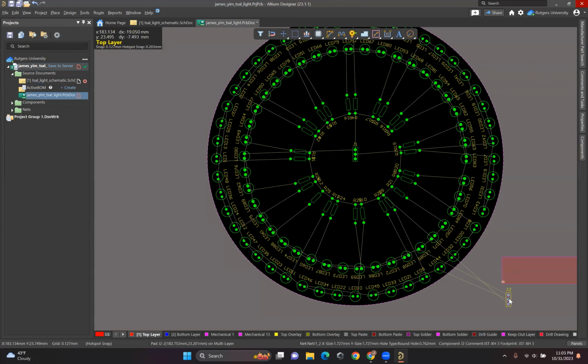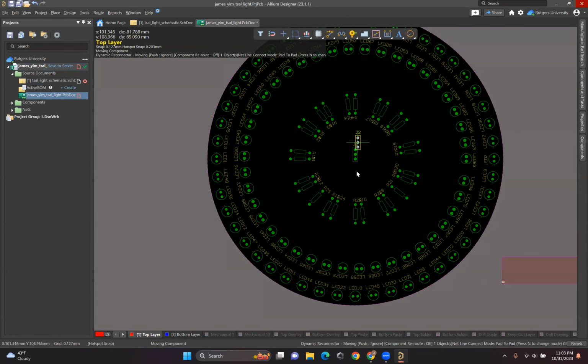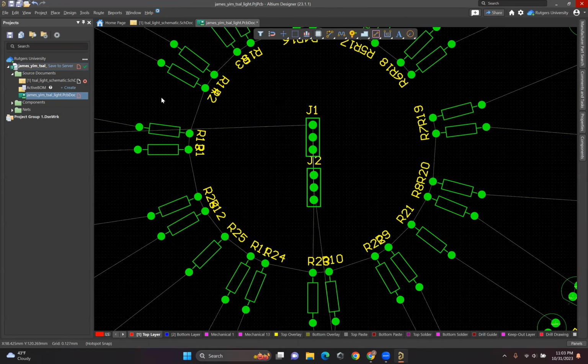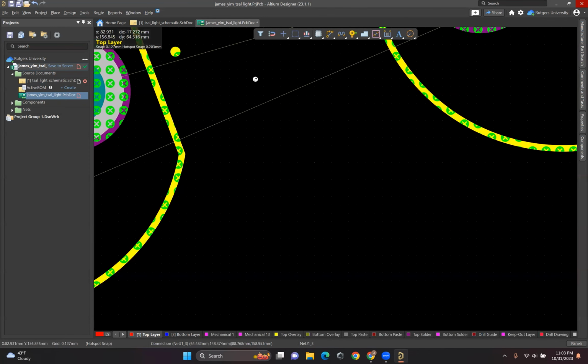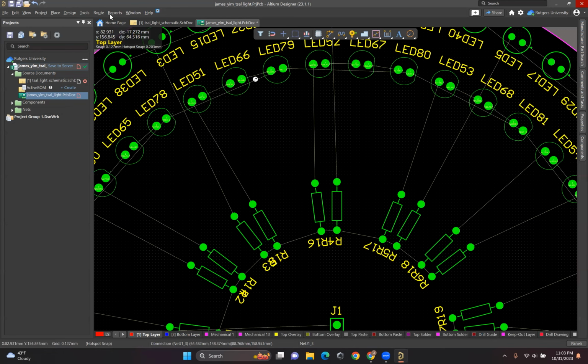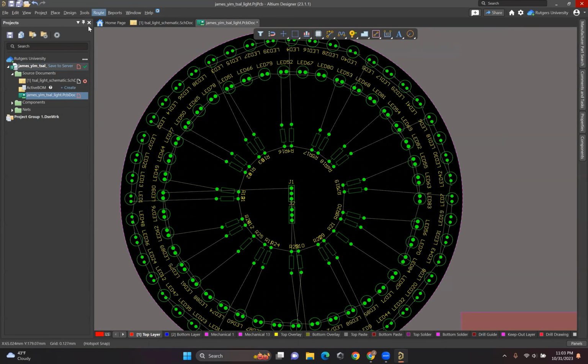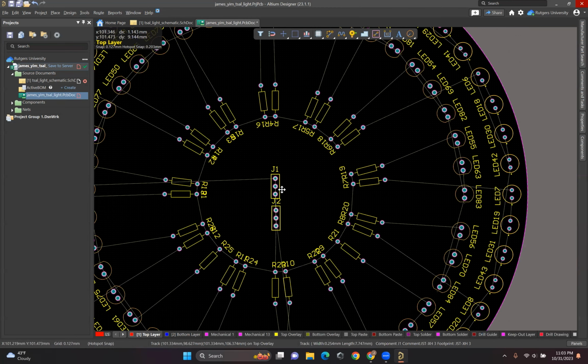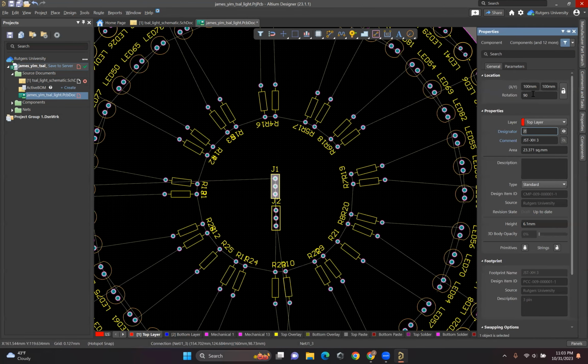Okay, so now I put a designator name on this. It's J2. Also, you might notice everything here is green. That's because there are error markers on them, because it doesn't follow the design rules, which you set up yourself. You just click reset design error markers, and it's going to get rid of it. Now I'm going to put all of these down.